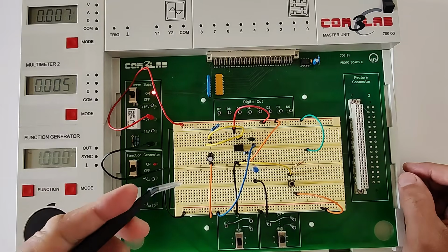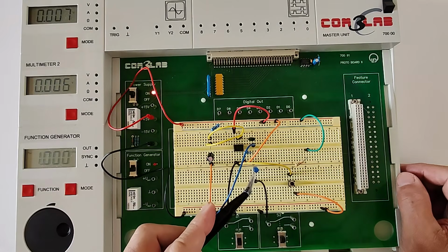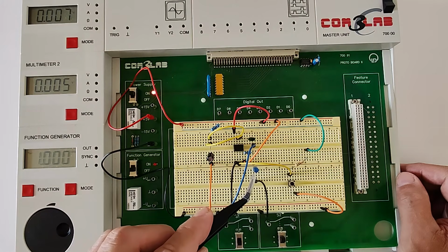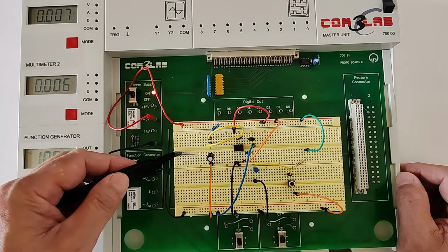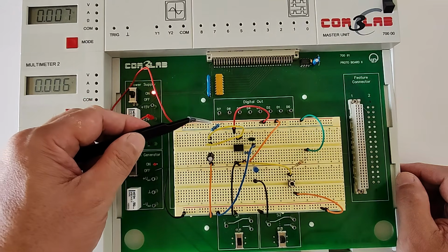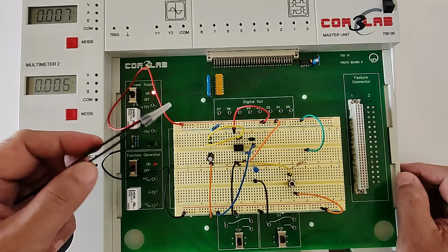Now, based on our theoretical discussion earlier, how long will that on state or that unstable state be? The period. What's the period of that on state? The period of the unstable state, where the LED will be on for a while, will be dependent on the value of this 47 microfarad capacitor and that resistor. Based on the formula, we could actually compute for that.